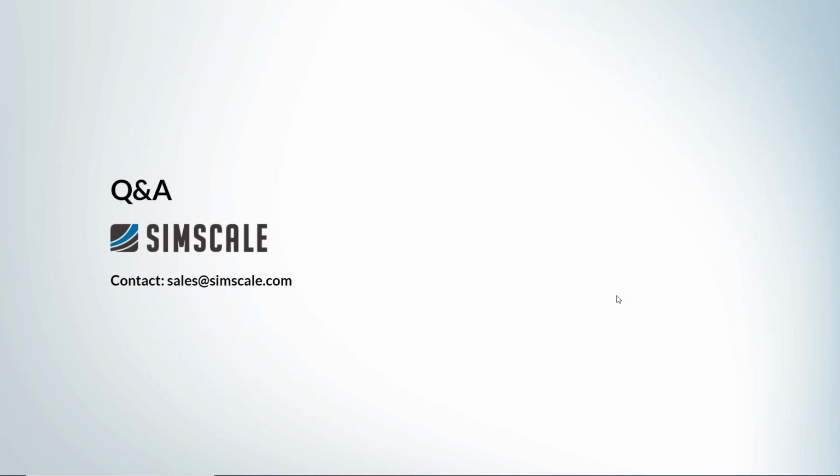Yeah, absolutely. So when we're setting up the wind data within the SimScale platform, you've got two options. You would start by typing in your location. In my case, it was Great Stone in the UK. Once you've typed in that, you've got two options. One, to import the data directly from our cloud connected service called Meteoblue. That is quite automatic, so you don't have to do anything. It brings in the data for you, and you can just select how many wind directions you want to choose. The other option is to upload your own weather file. That has to be a .stat file, and they're quite common.